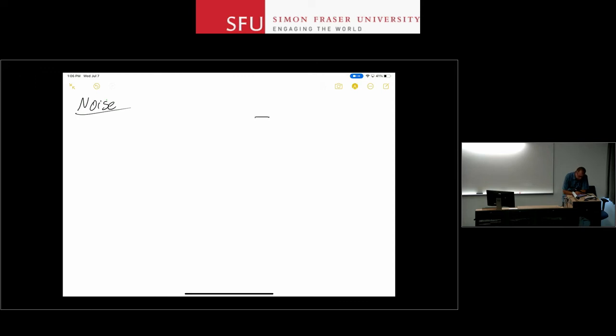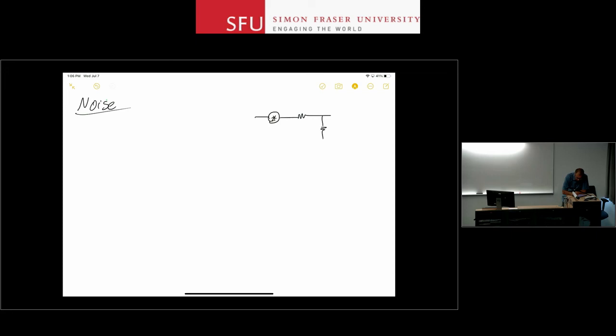So what I'm going to do is draw those two noise sources for the resistors in my model. Because it's a random source, I don't put plus and minuses across them. By putting a cross in there, I'm just indicating that this is not a regular voltage source, it's a noise source. So I don't have plus and minuses here. They don't really mean anything.